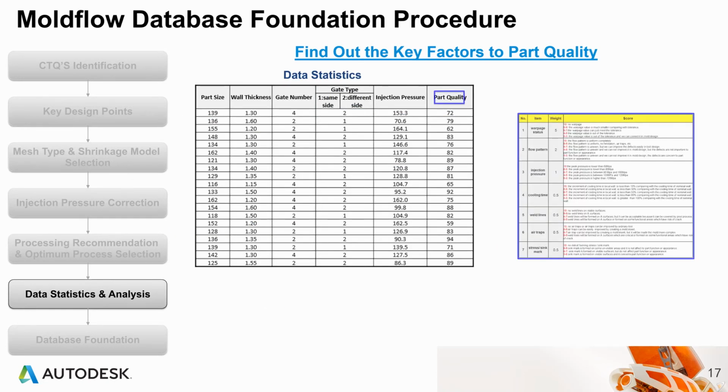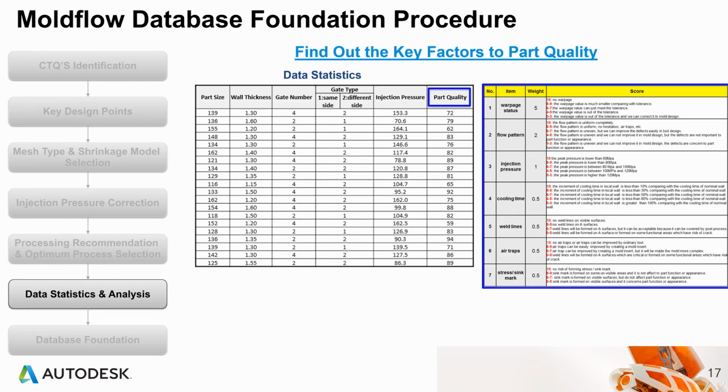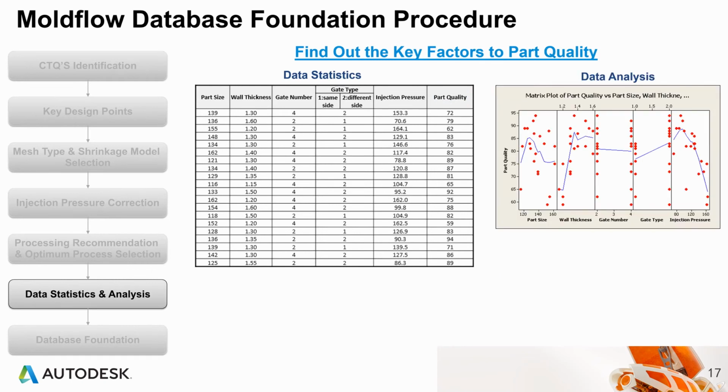And we also have a standard score system to evaluate part quality. After data analysis, we can see part size or thickness, gate type, and injection pressure are key factors.